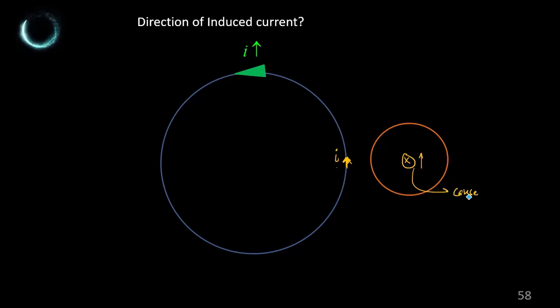So this is our cause effect. Okay. So that has to be nullified. That means I have to reduce that effect. To reduce that effect means I have to decrease the cross, but I cannot decrease it. So what I can do as an opposite effect, I can increase the dot. So dot increase is the opposing effect, I identified that. So once I identified that the increase of dot is the opposing effect, you have to place your thumb towards yourself and rotate the finger. Once you curl the finger, the current will be in the anti-clockwise direction. That is the induced current.